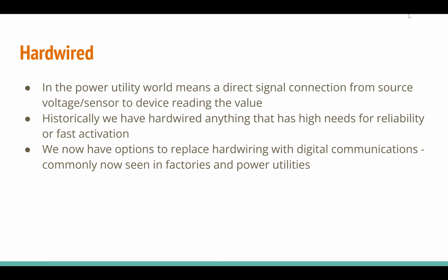Well, you can have a relay capturing information as well, but that's not SCADA at that point, right? So when we have a relay capturing information, but we're not calling it SCADA, that's because the data is generally hardwired.